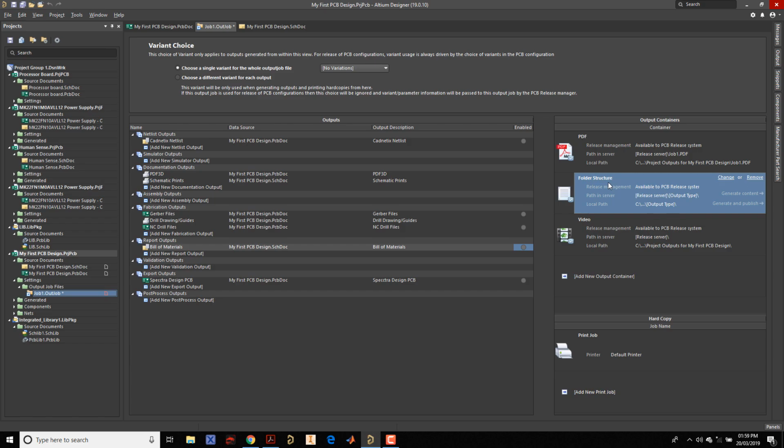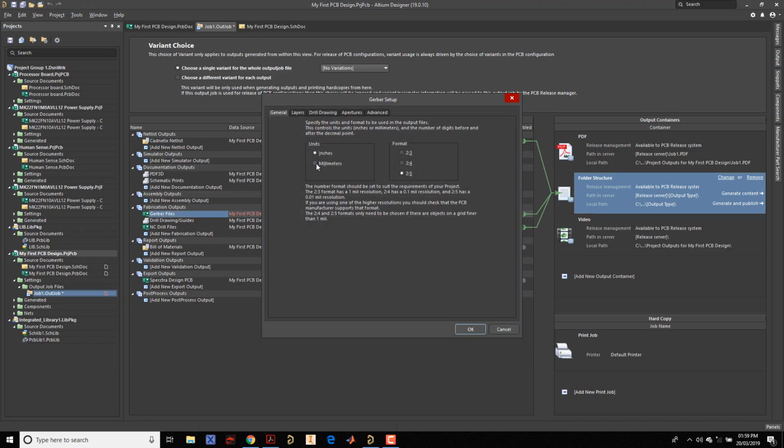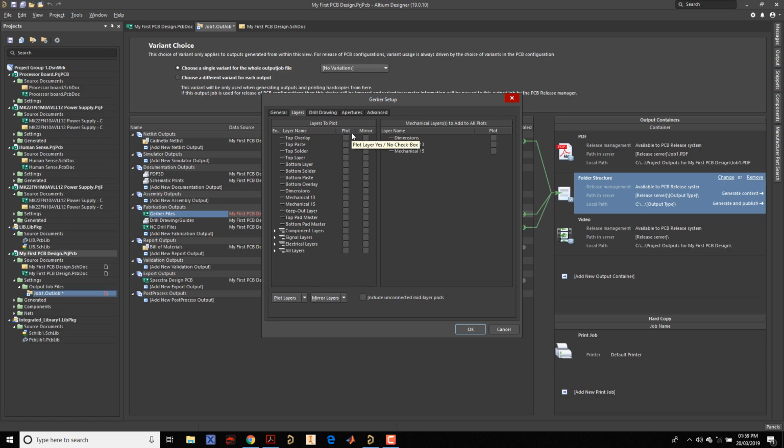And then the files, the Gerber files. I want CAD, the net list. I want Gerber. I want NC drill files, but I don't want this, and I don't want that. Good. So basically, I'm done. What is left is to configure these Gerber files. Push it to millimeters. Leave it there. 4:4. Layers: which layers did we use? We used the layers top, paste, this, that.